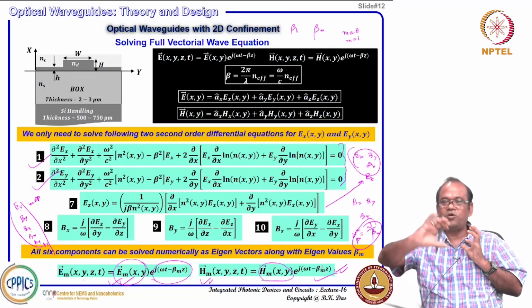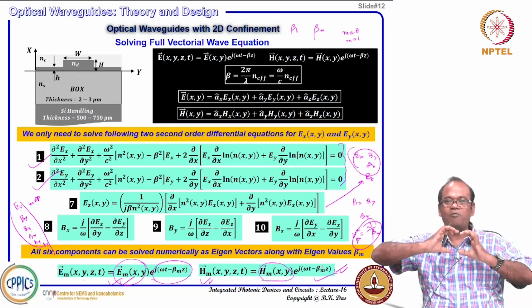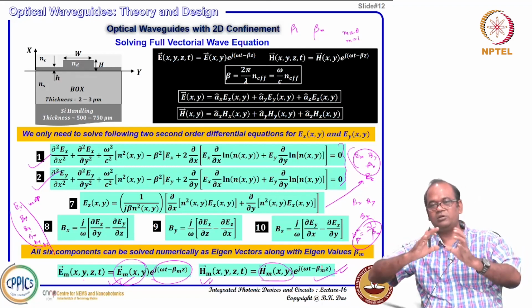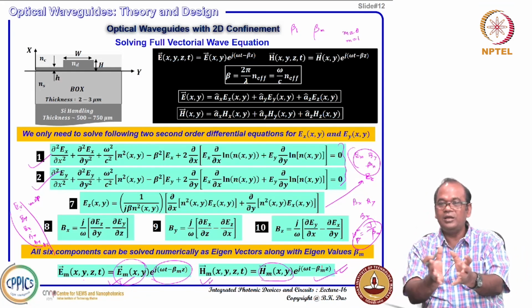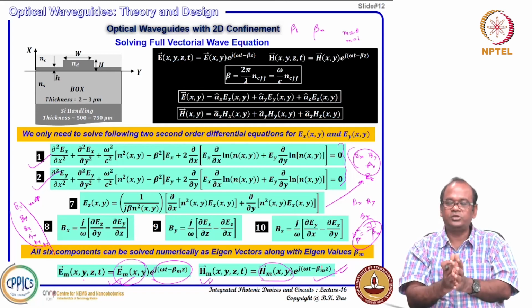As long as your waveguide is maintained uniformly, that 1 watt will be carried by mode 1, another 1 watt by another, and they will not exchange power in between. That is the beauty of the eigenmode solutions, and practically that is true.